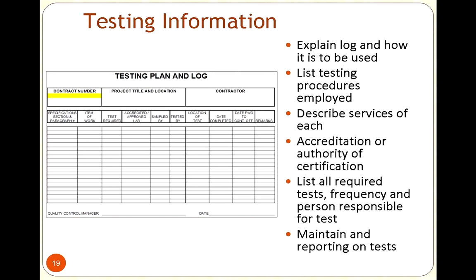The other thing about the testing is, if you're doing any testing or you have something tested, then document it here. So if somebody said, hey, we see these 9-inch floor tiles in a school, and anybody who ever thinks about 9-inch floor tiles, sometimes the first word they think of is asbestos. So you may say, for example, no, I've had it tested and the test came back negative. These don't need to be abated. They're not pretty, but they don't need to be abated. So testing like that might happen along the way before a construction job comes up, that's some good things to document.